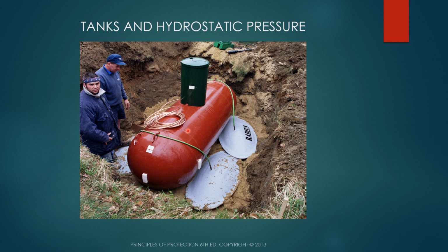Always, always, always. I don't care where you are. The water table is going to reach the surface up here. So make sure that whatever this is, you can put these tie downs on. And by the way, whenever you have a round cylinder, the starting point on the backfill is 75% of that diameter. So if you have a 4-foot diameter tank, you want to have 3 feet of soil on top of it. That's how you start.